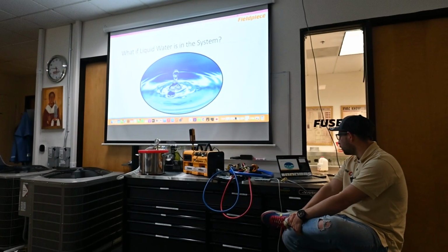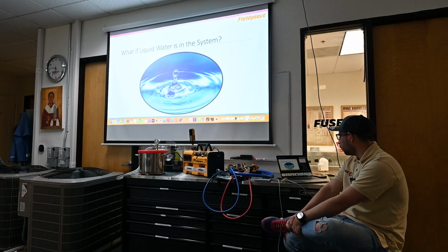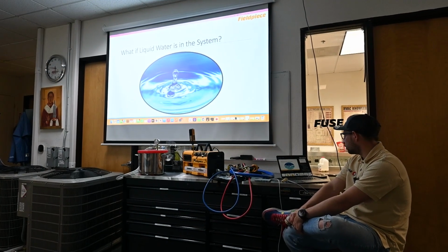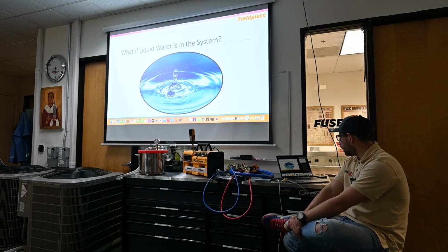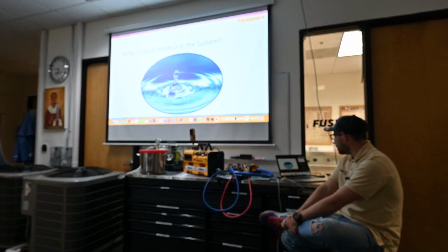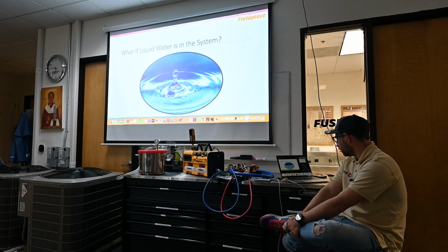What if liquid water is in the system? If liquid water is present in the system, get 99+% of the liquid water out prior to starting the pump. A very small amount can be removed with the pump, just a very small amount. A large amount will be time consuming and use a lot of oil. Expect to change the oil in the middle of the process, so have plenty on hand.